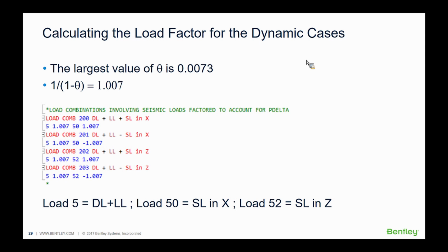And you should be in compliance with the code requirements. So let me go back to the model and explain how the P delta analysis is set up for all these cases, except the dynamic, and how a first order analysis is set up for the response spectrum case.